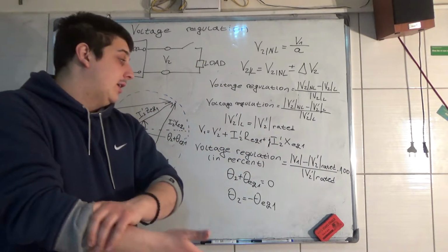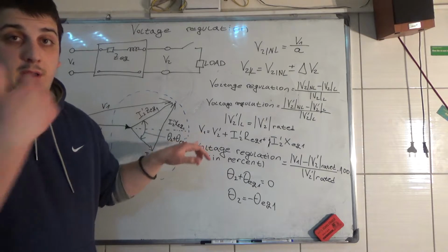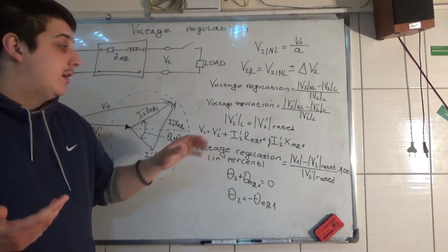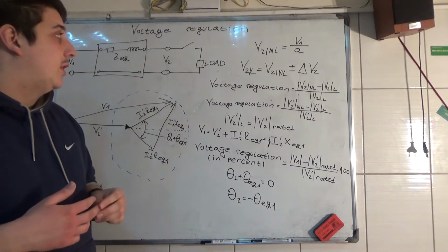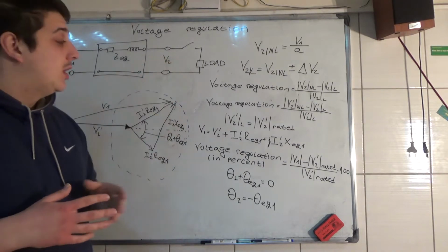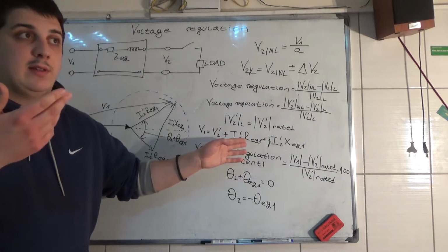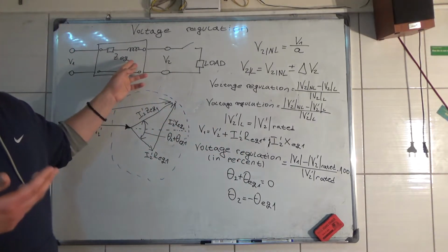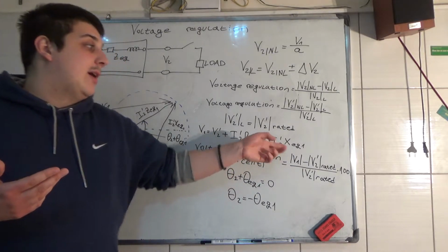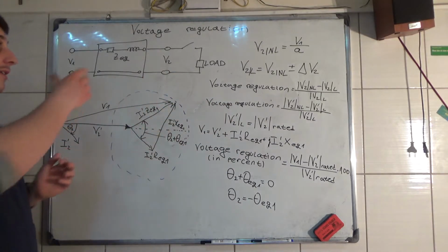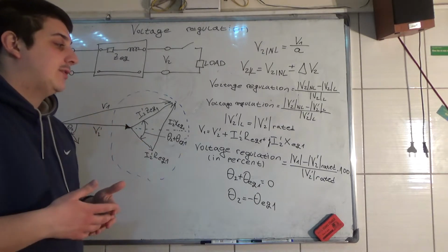on the nameplate. Now, this is a formula: the primary voltage V1 is equal to V2 prime, the load voltage here, the terminal voltage, plus I2 prime times the resistive equivalent part of the internal impedance of the transformer, plus j I2 prime times the reactive impedance part of the transformer.